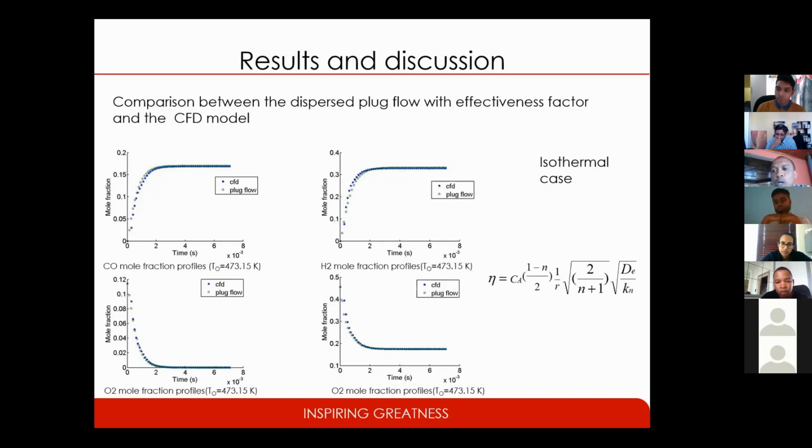But when I had those 2 heat transfer equations linearized in the way that I've done, I was able to use that in the modified plug flow model. So it gave me the result that I had because it accounted for the interaction through channels. Because if you have the pseudo-homogeneous approach that I spoke about, but you don't have the linear combination of those 2 analytical solutions, then it won't give you the correct temperature profiles. So it did help me in that fashion.